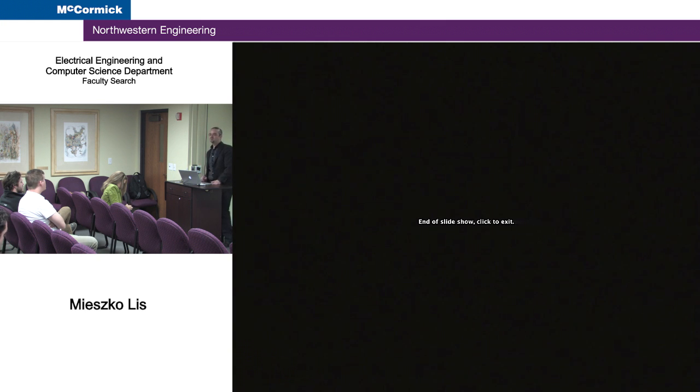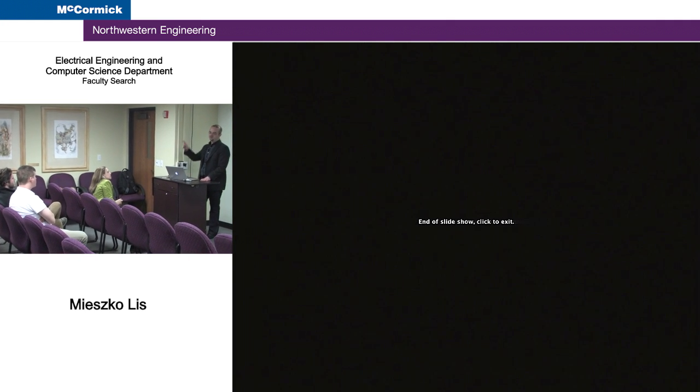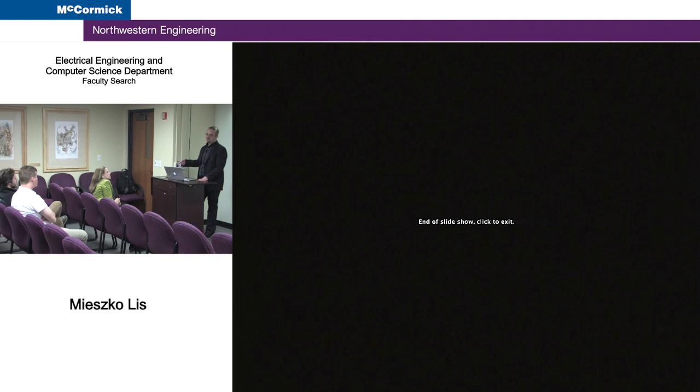It has to do more with how much you can amortize by moving the threads than with what application you're running. So 4 for us turned out to give the best results. That is not to say that this is the case for all applications. It also depends on what the access patterns are. For example, if you always access data on the other side of the chip, then maybe you need more.